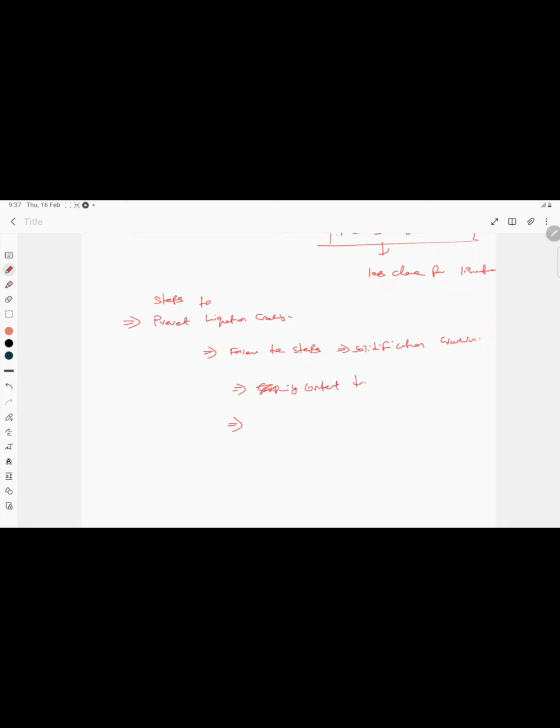Then, fully austenitic structure is also not recommended. Some ferrite presence will help us to prevent liquation cracking, as we have seen in solidification cracking, since it has the capability to absorb impurity atoms like sulfur and phosphorus.